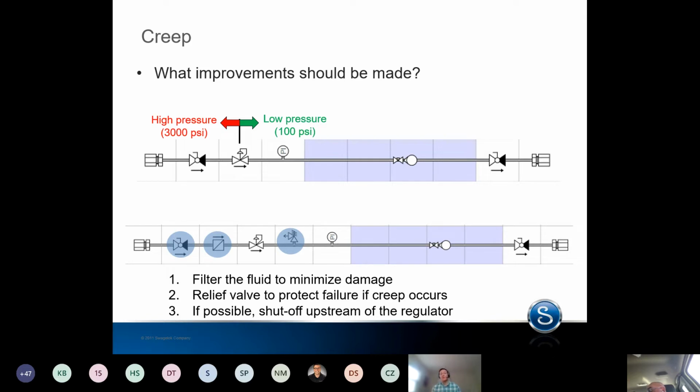And really the biggest distinction there is that unlike something like a needle valve, where if you need more closing force, you can turn that handle and even get some tools out if you want to and really wrench down on that seat if you absolutely need to make a seal. You don't have that luxury with a pressure regulator, right? So you need to rely on that poppet spring and your inlet pressure force to shut off the regulator, and that's all you get. There is no additional closing force to be added. So if you can, take that burden off of the regulator and shut off upstream.